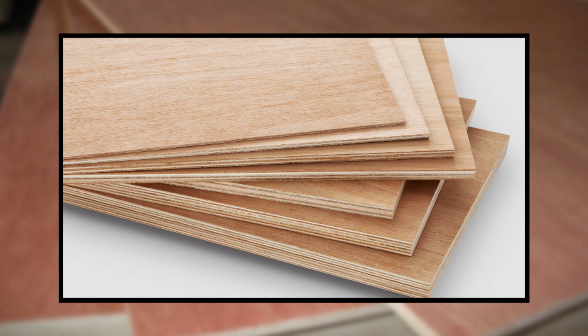Plywood is an engineered wood sheet material made of 3 or more thin layers of wood bonded together with an adhesive. Each layer of wood or ply is usually oriented with its grain running at right angles to the adjacent layer in order to reduce the shrinkage and improve the strength of the finished piece. Most plywood is pressed into large, flat sheets used in building construction. Other plywood pieces may be formed into simple or compound curves for use in furniture, boats, and aircrafts.